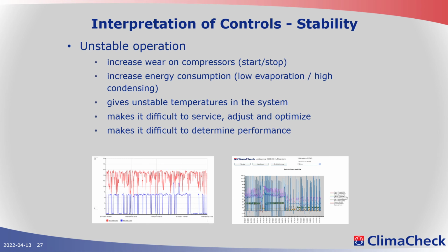And of course, you should not force up the condensing because it will cost you more in compressor wear than in fan power on almost any system. It's extremely rare. I don't know if I've seen a case where you save more money on the fans than what you spend on your compressors when we are talking about this type of high set points for condenser fans.